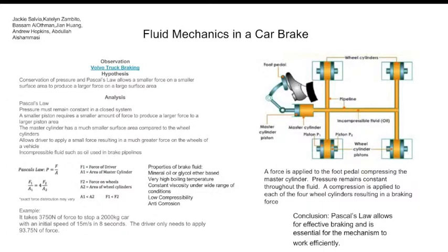The main concept behind hydraulic systems is Pascal's law. Basically, Pascal's law says that the pressure has to remain constant at all points of the fluid. So, when a person applies a small force on a brake pedal, the area of the master cylinder is very small, and the pressure has to remain constant. Therefore, the force applied near the brakes will become much larger because the area of the cylinder near the brake is much larger.